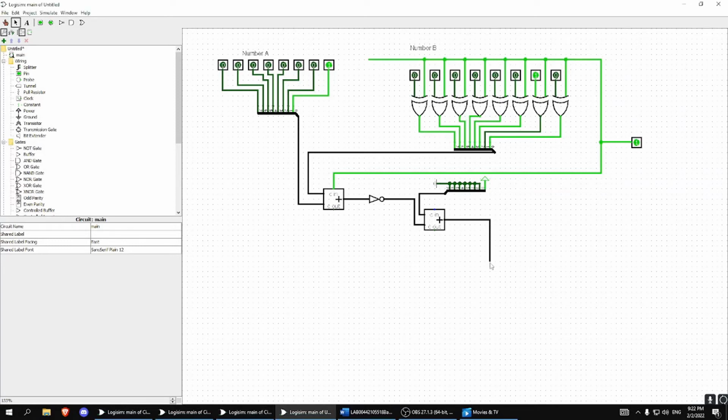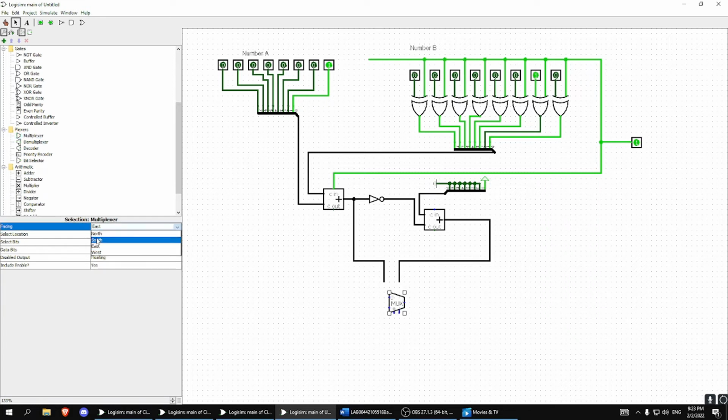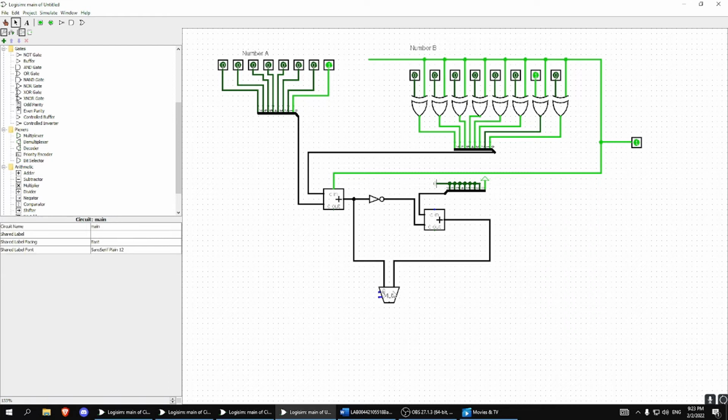So we could put this through a multiplexer, which looks like, sorry, you have to use this one, which looks like this, and we need to put this multiplexer facing south with 8 bits output and input, so here and here. And we need to signal to this multiplexer which one of these we would like to use, since a multiplexer is essentially kind of like a railroad we could use. So let's do that now.